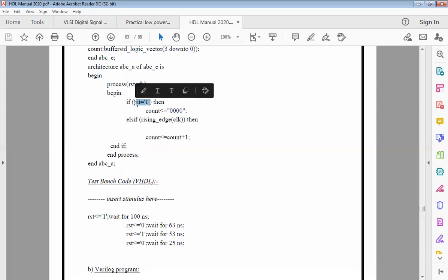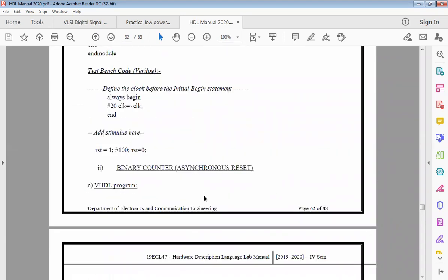Reset is ultimately, you should understand, when I reset something, whatever are the values there, immediately it will be nullified. Suppose the counter was counting and it came to say 55 or something. As soon as it finds that reset has gone high, which means that 55 which it had counted previously should actually go to 0. And counting will happen in the next clock, right? So resetting is happening irrespective of the control of the rising edge of the clock, right? So reset has more priority here. Hence the name asynchronous reset.